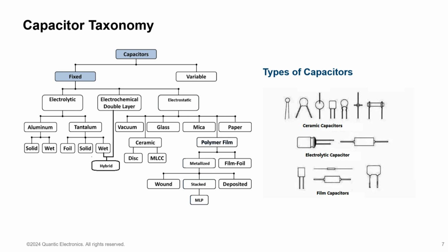The last subset, supercapacitors, are not pure capacitors. They actually combine a double layer of electrostatic capacitance paired with an electrochemical reaction, similar to what is seen in a rechargeable battery. So the electrochemical reaction results in a pseudocapacitance because the voltage discharge profile mirrors that of a capacitor rather than a battery.